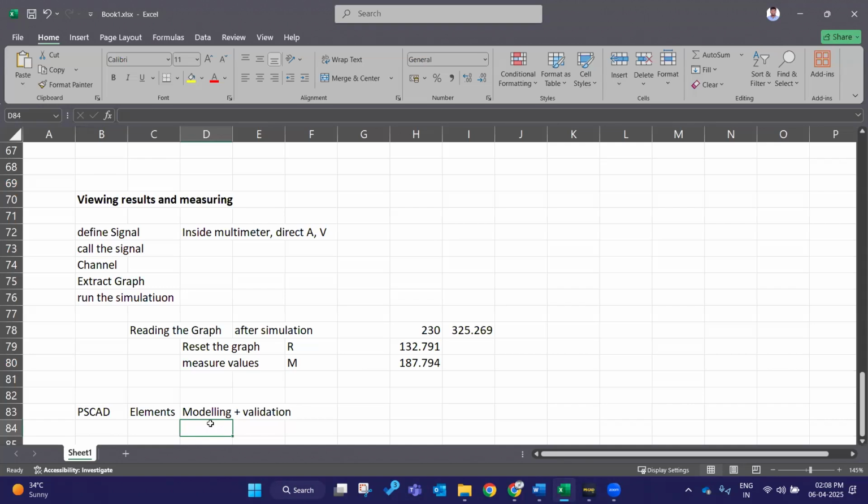After entering those, for example, if my three-phase short circuit current is 50 kiloampere, then after modeling the source I want to check whether that source is capable of supplying the 50 kiloampere when it is subjected to a three-phase fault. Hope I'm clear.